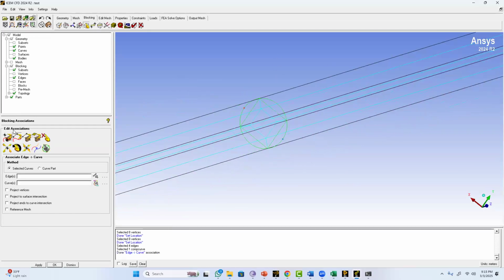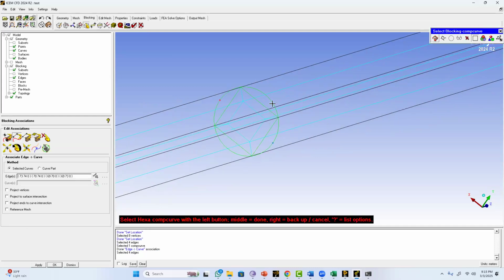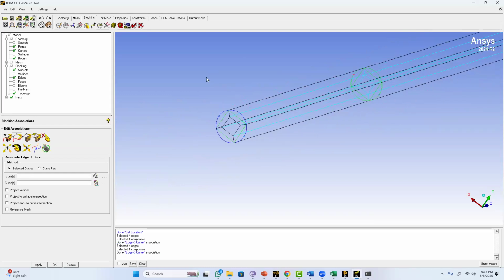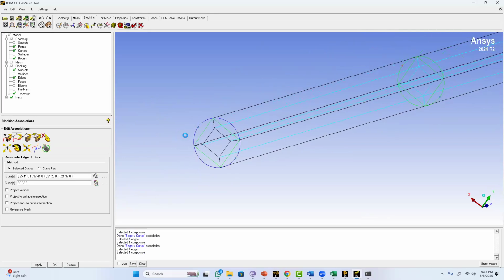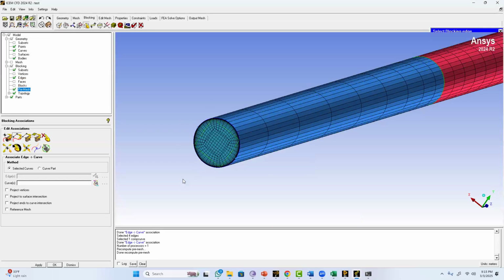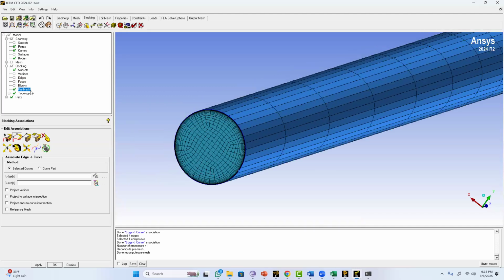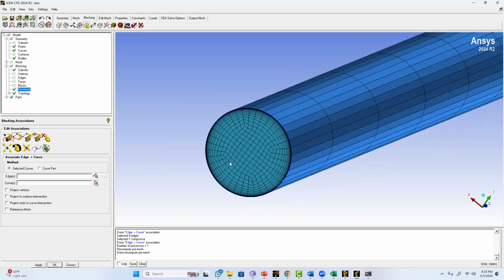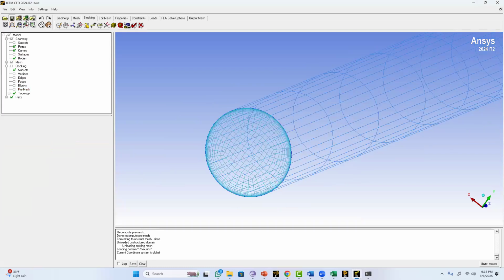In the middle, if you want, maybe this is on the safer side, so I will do that as well. And then this end only for the outer edges, which refer to our geometry. That's all. So display the pre-mesh, right click on the pre-mesh and convert to mesh. That's all. So now we made the mesh on the new geometry. Very simple. Any questions?